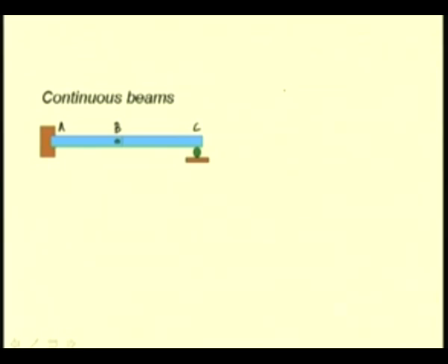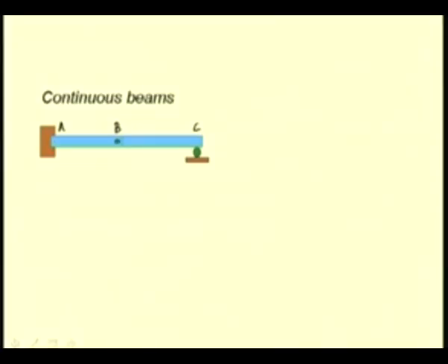because we have already discussed that if we remove a structure from its supports and it collapses, then we cannot consider the free body diagram of the complete structure. So, in this case, if we remove this structure ABC from its support, obviously it collapses, that means the beam can rotate about this point B. So, we consider the free body diagram of the dismembered beam.